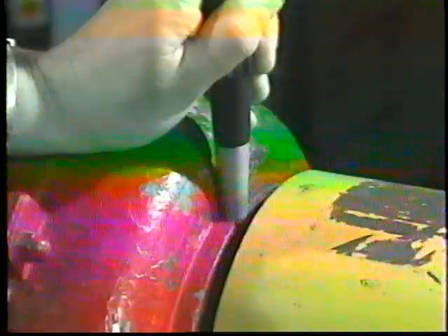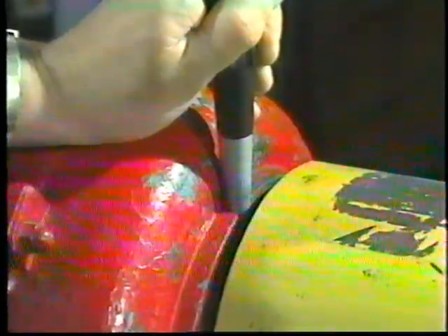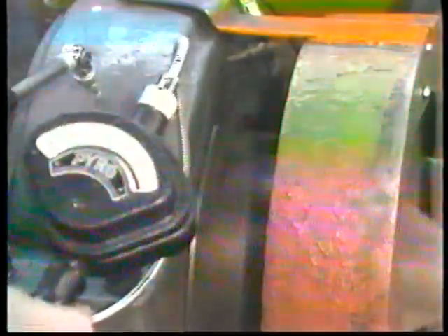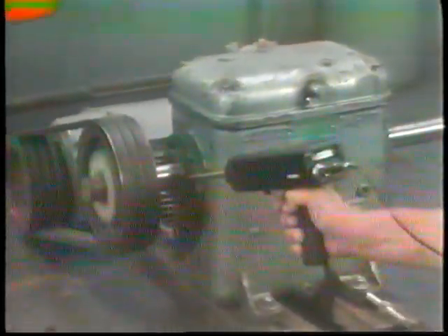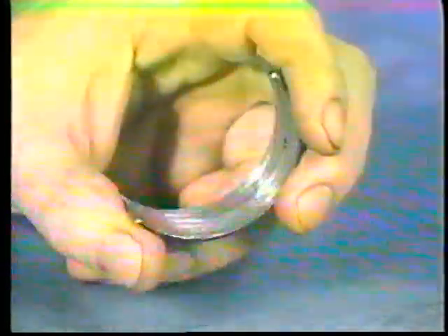Tools such as this temperature probe will make checks of bearing temperature quick, accurate, and safe. Some bearings run hot enough to burn you, so using a probe is safer than touching the bearing housing. You should also listen to the noise the bearing makes. Sounds will often indicate the bearing condition. Experience can help because you can become familiar with specific machine sounds, or you can compare sounds to those in similar applications. In a plain bearing, knocks and thumps are an indication of slackness.